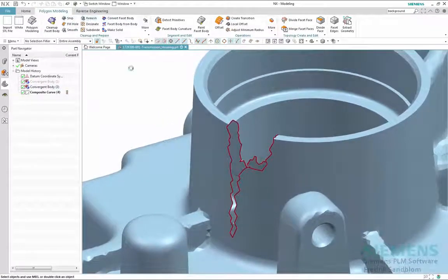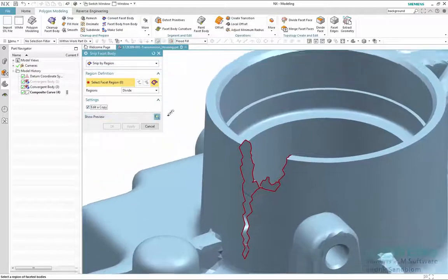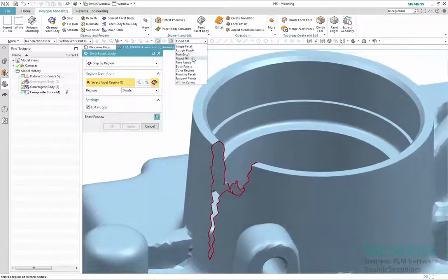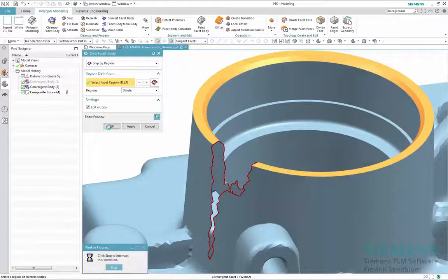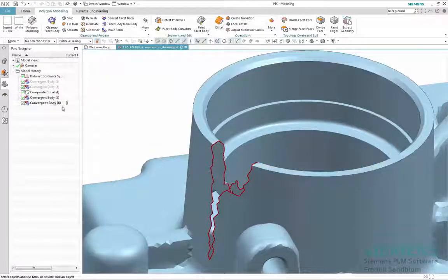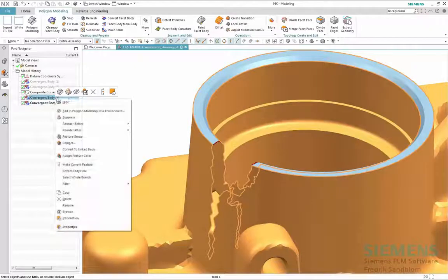Since geometry is missing, we use the existing geometry bits in the direct connection to the damaged area in order to create some support geometry. Here we once again use snip to create a copy of the top of the axle outlet to create a limited copy of the area that we will reuse. The additional copy we will get when performing the snip operation. With the copy option on, we simply delete as we do not need it.